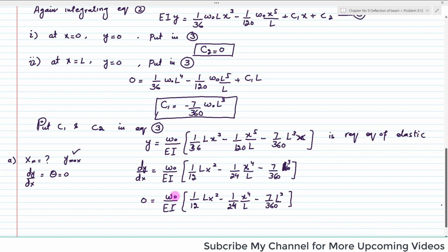As w naught over EI is constant, it is not equal to 0, so the product of these two being 0 means only this term is equal to 0. So I will write 0 is equal to 1 over 12 Lx square minus 1 over 24 x4 over L minus 7 over 360 L cube. Clear?